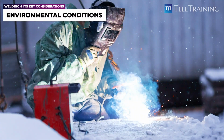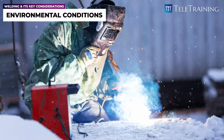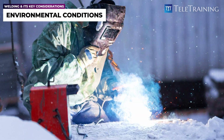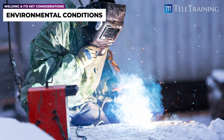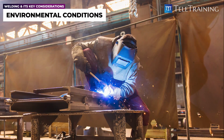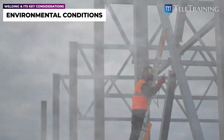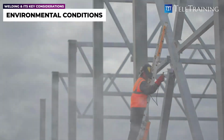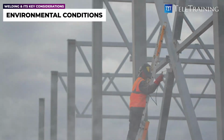Or, welding in cold temperatures may require preheating the base metal. Otherwise, the significant temperature changes during the weld process could cause deformations in the metal. Also, when welding in windy weather, we should use wind shields around the welding areas, since the wind can impact the shielding gas of some equipment. And dust and other foreign material can contaminate the weld and impact its quality.